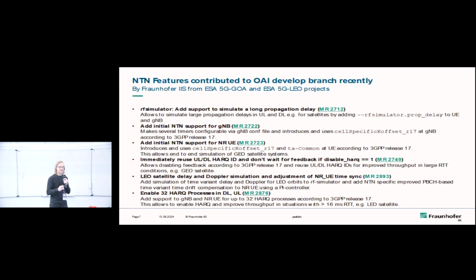Yes, then the next thing is, with these 3 merge requests in the beginning, it was possible already to have a complete simulation, and also with PropSim, an emulation of an end-to-end geostationary satellite. But to improve the throughput, because we were still using HARQ processes, with the 16 HARQ processes and this round-trip time of 500 milliseconds, the throughput is extremely limited.